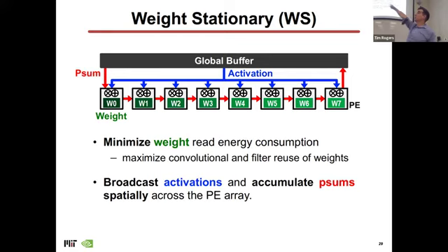And then you go to the first processing element, and you get that small part of the partial sum that's related to weight 0 at processing element 0. Then you pass that partial result out to the next processing element, which adds the influence of weight 1, and you pass that all the way along until you're finally done with all the weights, and then you spew the output back out to the buffer.